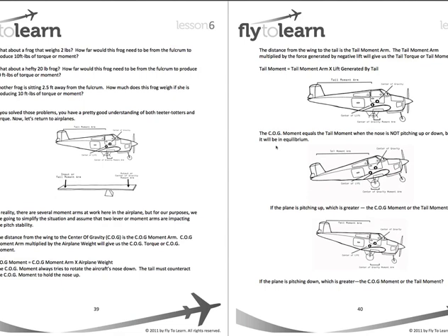Now we go back to an airplane. And we look at the center of moment, center of gravity, and we walk our way all the way through it with the kids. And for example, we say tail moment equals the tail moment arm times the lift generated by the tail. Remember, we're not saying you necessarily have the weight of the tail alone. Usually there's lift generated, many times in just the opposite direction that the wing lifts. Assuming most of the time lift on a wing is going straight up in the front of the airplane, the major wing. The tail, for example on the Cessna 172, the lift is pointed down. So you've got that downward force pressure on the tail, times this moment arm.